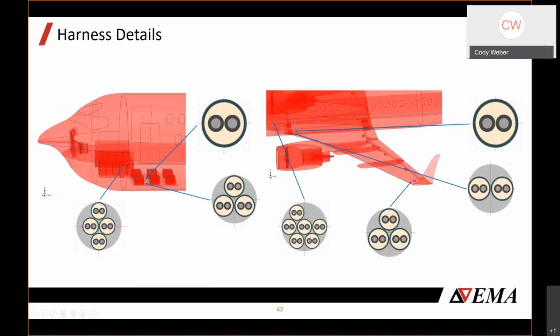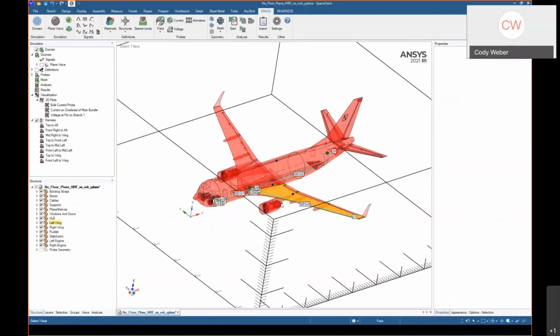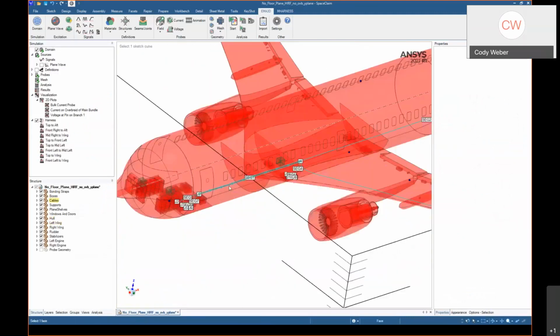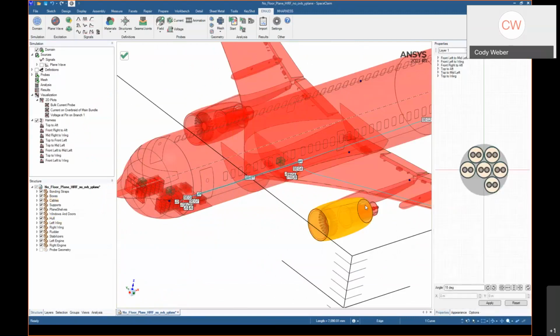And I just wanted to pull for a second here what the tool looks like. And so that as you have this tool within your interface here, you can go in and you can visualize on these cables what the packing looks like. And we have lots of capability for adjusting this packing if that's something you're inclined to do. I have done some studies in the past, and as you rotate and move the cables around within the packing, that can help to disrupt the modes and resonances associated with cables.